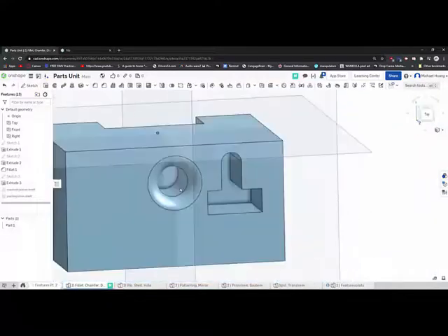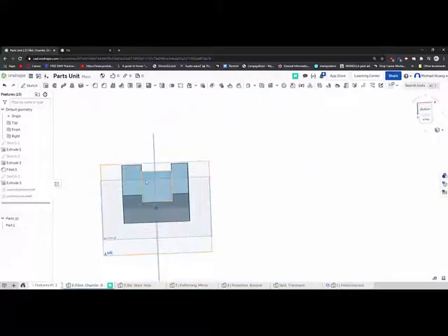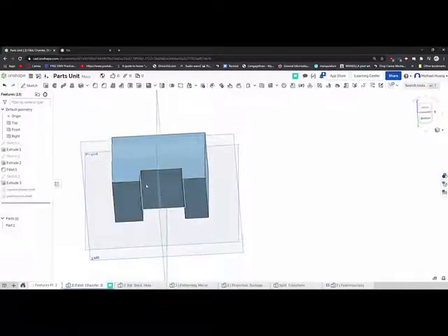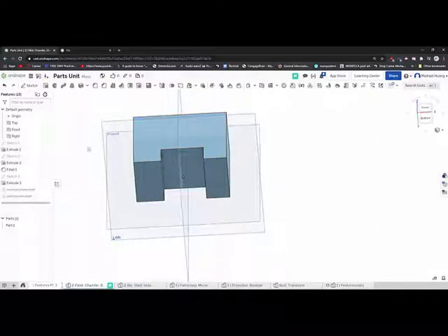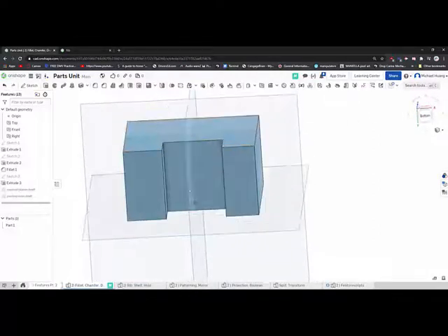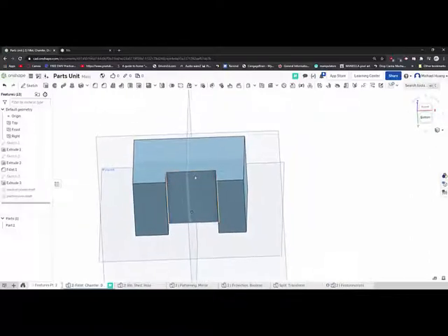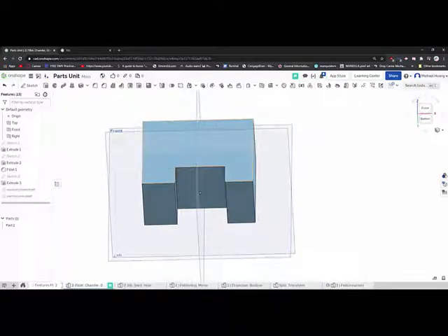All right. So fillets are useful for CNC. So when you're actually cutting out your part in a workshop with a CNC machine, let's say you're creating it out of like a block of wood and using this cylindrical bit. So it's like a cylinder that's spinning really rapidly, right? And you're cutting through this material. Now, you won't be able to make this exact piece with that cylindrical bit.